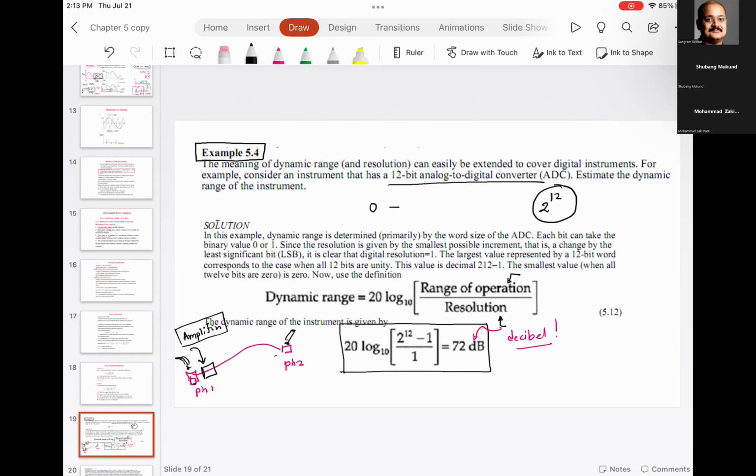So they had to characterize what the loss is at 10 hertz, what the loss is at 20 hertz, what the loss is at 30 hertz. So basically, sing a monotone at 10 hertz, ting, ting, ting, then a monotone at 20 hertz, and see what amplitude you receive at the receiving end. And you will see the range would be 1 to 10,000. You cannot plot these on a single linear scale. So they created this log measure that could take this wide variation and fit it into a reasonably representative graph.